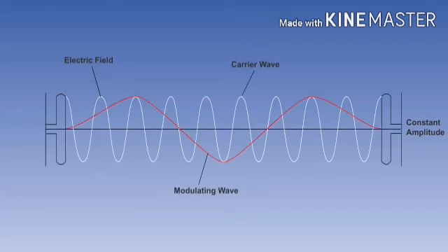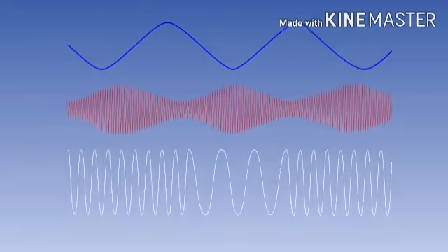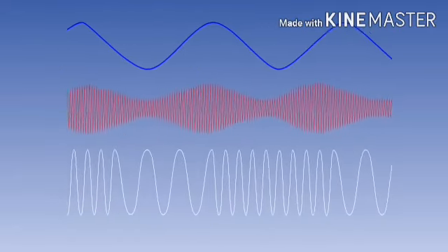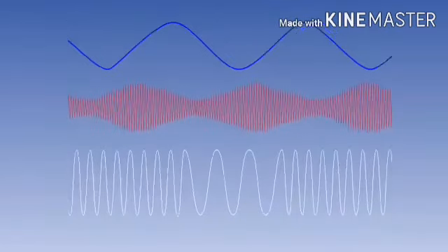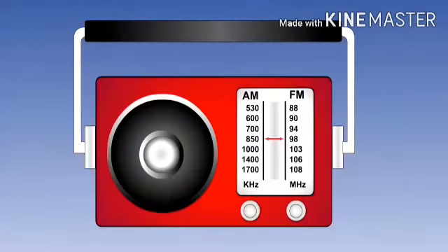We now need to look at how information, called intelligence, is superimposed onto the radio wave. When this is done, the radio wave is termed a carrier wave, and the intelligence is said to be modulated onto it. More sophisticated intelligence can be superimposed upon a carrier wave by modulating either the amplitude of the carrier wave, AM, or modulating its frequency, FM. You will be familiar with the term AM radio. This means amplitude modulated radio and refers to the medium wave broadcast band 300 to 3000 kHz.